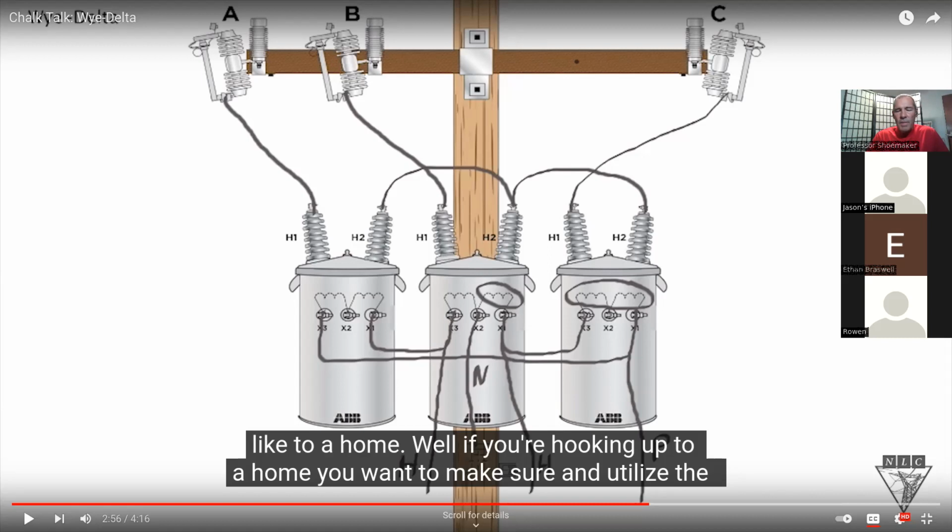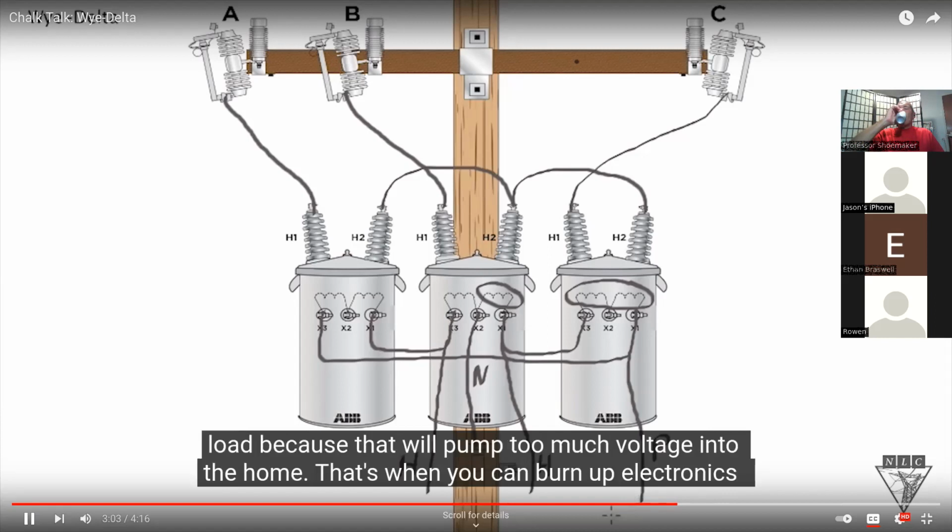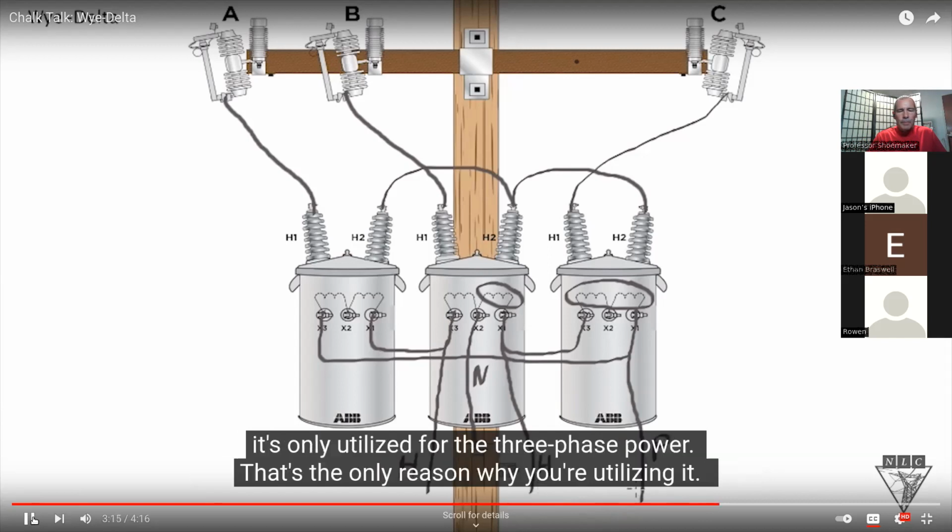And we're going to get some actual photos here in a little bit showing you open delta banks and closed delta banks and Y banks in the air. So it gives you a better idea of what's going on in the real world. If you're hooking it up to a home, you want to make sure and utilize the two hot legs and your neutral. You don't want to hook the power leg up to the single phase load because that'll pump too much voltage into the home. And that's when you can burn up electronics like computers and TVs, things of that sort. So you always want to identify your power leg, and it's only utilized for the three-phase power. That's the only reason why you're utilizing it.